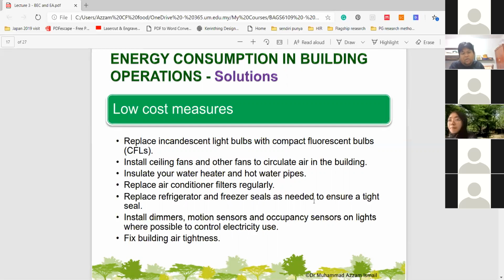Okay? You don't really have to call in the technicians to come in and clean it out for you. You can do that at least perhaps once every 2 years or so. It doesn't have to be so regular. Let's say if you need to top up your gas, you probably call somebody in and get that person to clean it up, clean out the diffuser and also clean out the compressor outside your building. So both will have to be washed and cleaned properly.